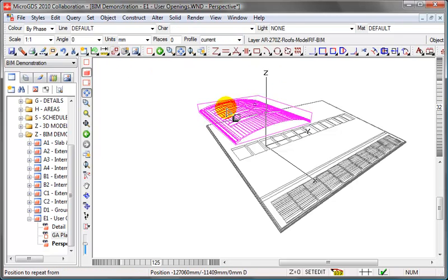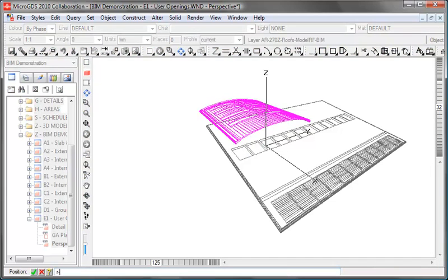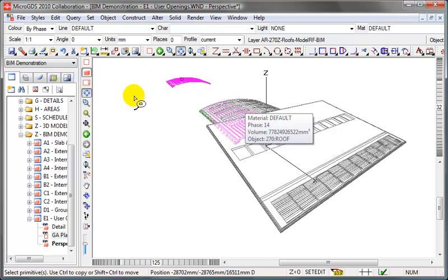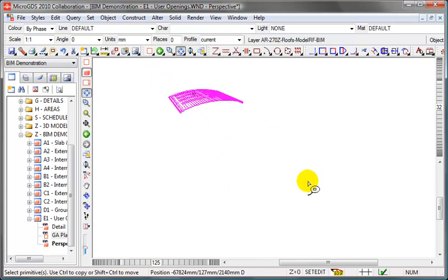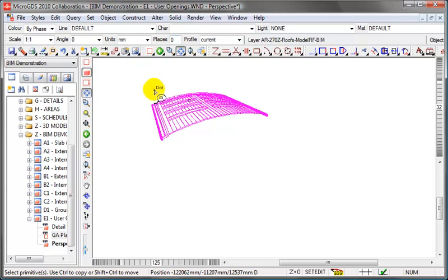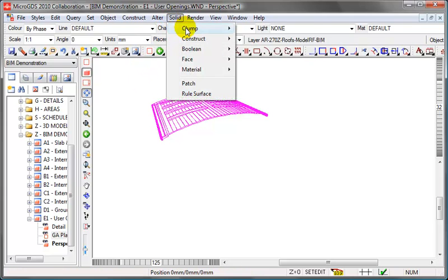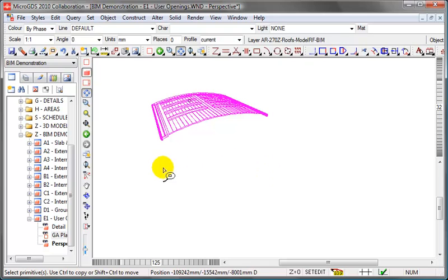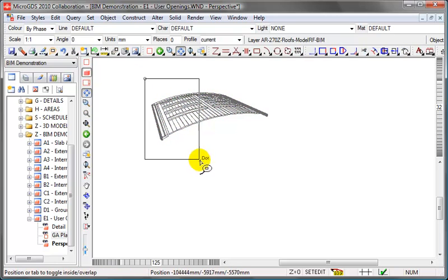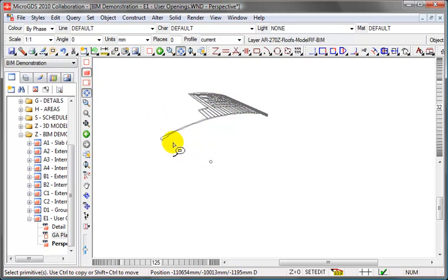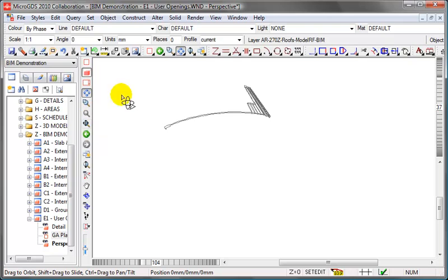And let's copy this roof here 100 meters away in the x-axis, and that gives us a duplicate of the two solids that make up the roof itself, which we can then convert to 2D graphics. So for solid, clump, unclump, so all of these surfaces are now outlined with 2D lines. Select all of the graphics apart from these two curves that form the end of the roof. Need to orbit a bit more, so we can select just those pieces there.